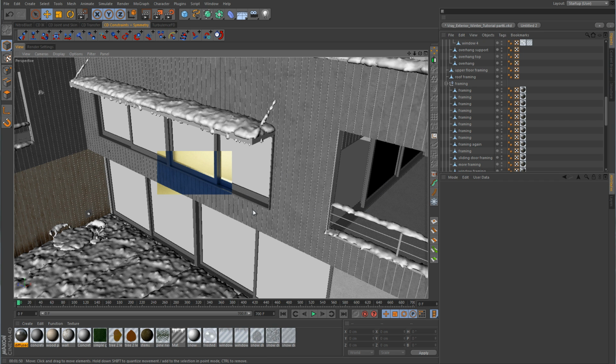Okay, so you can see that these metal textures look really nice, and the render time went up a little bit because we're using reflection, plus we're blurring it, plus we have the area light, plus we also have the blurred transparency on the windows. So the render time you can see down here was 1 minute and 50 seconds.